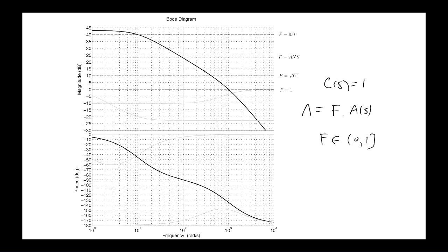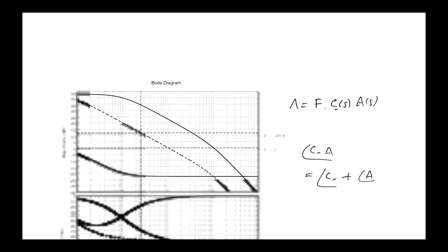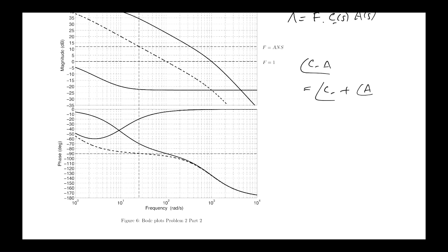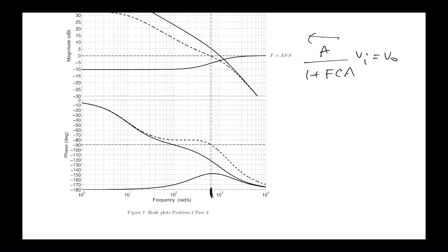Yeah? Any other questions? Yeah, and when you're building electronic circuits, if you can avoid putting components in, you would avoid putting components in. So the lag compensator is not doing anything much relative to just having the resistor divider network in there. So why would you put it in there? But for the lead compensator, all you're having to put in to that little box that I drew is one more resistor and one more capacitor, and you can see that it widens the bandwidth significantly.